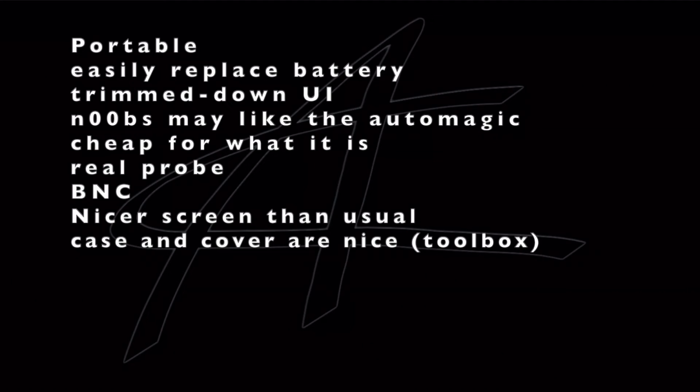It's pretty cheap for what it is if you look at just the specs, but again, with all digital scopes, the specs can be smudged and you might not even know what's going on in the background. For example, you're not getting the full sample rate when you go to particular sizes.